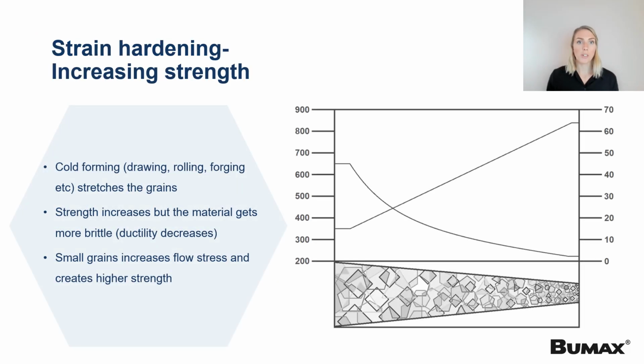The internal structure of the metal is organized in fibers. Cold forging allows control of the orientation of these fibers and makes it possible to obtain very high mechanical strength characteristics. As strength increases, the hardness of the material and ductility generally decreases.